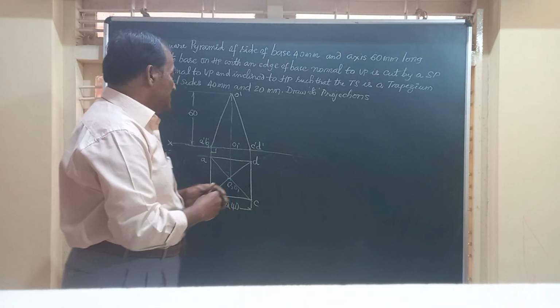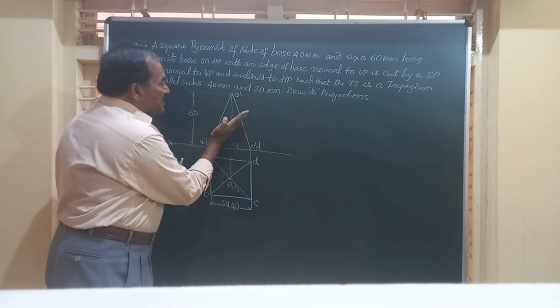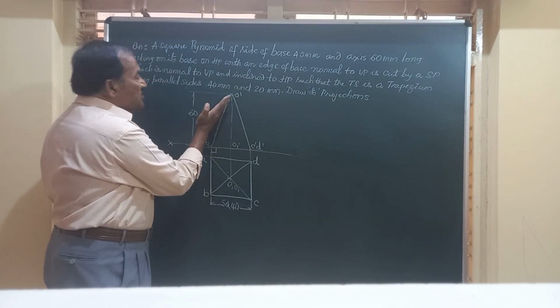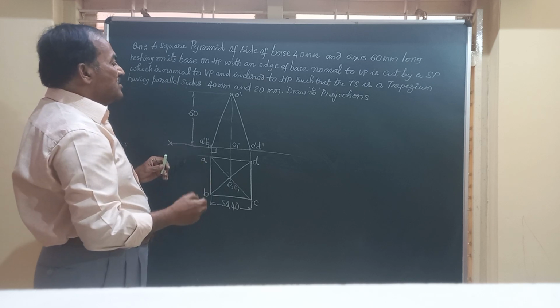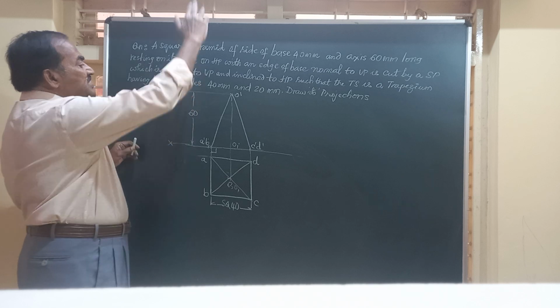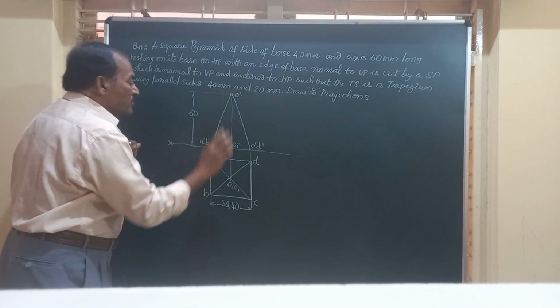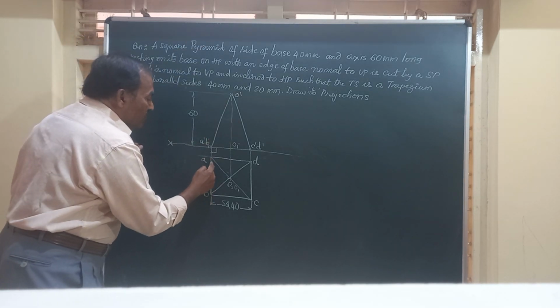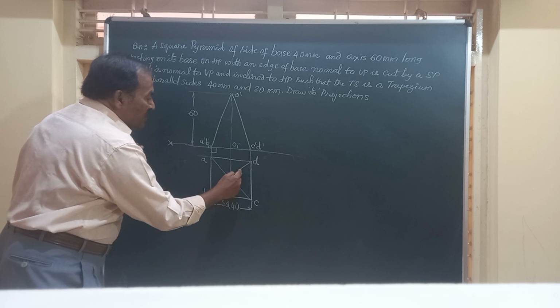But he says when it is cutting at an angle to HP, the true shape you are going to get is going to be a trapezium. So friends, in the top view, you will have 4 points, 2 passing through A and B and 2 on the other side.